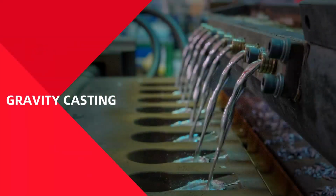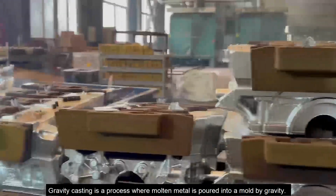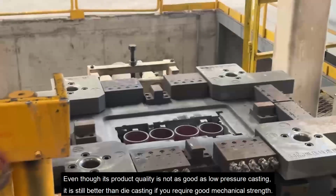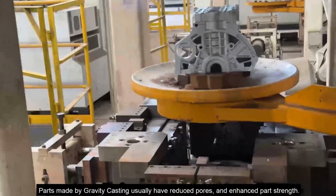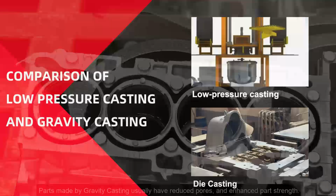Gravity casting. Gravity casting is a process where molten metal is poured into a mold by gravity. It is generally used in non-ferrous castings such as aluminum and brass. Even though its product quality is not as good as low-pressure casting, it is still better than die casting if you require good mechanical strength. Parts made by gravity casting usually have reduced pores and enhanced part strength.